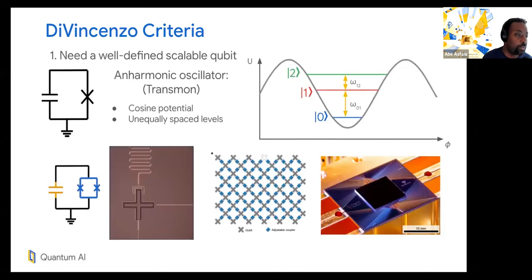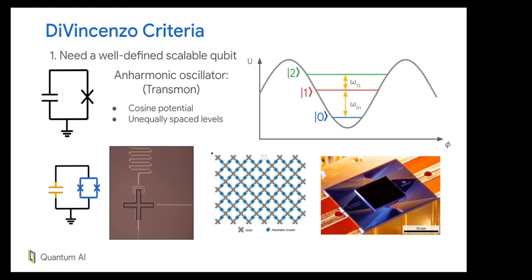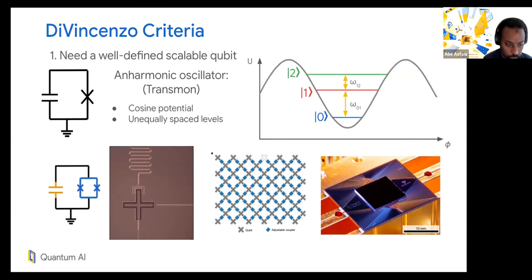Now, this is all fine and good, but if you really look at the papers, for example, these are pictures from our Beyond Classical experiment, you'll see pictures that look like this. So here's, for example, the device. What it really looks like is the chip is flipped onto another package. You have the qubits on one chip, you have the wires that connect to the outside world on another, and the qubit chip is flipped onto the other one. Together, these two form the quantum computer that is then packaged to the outside world.